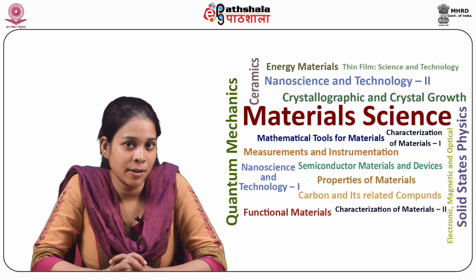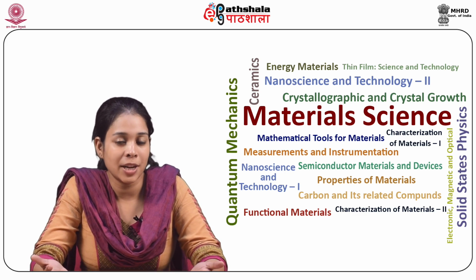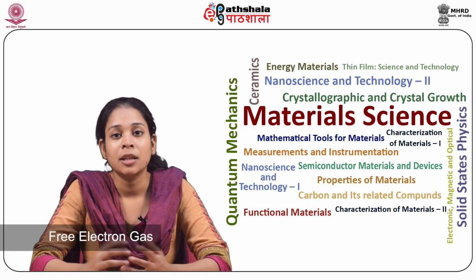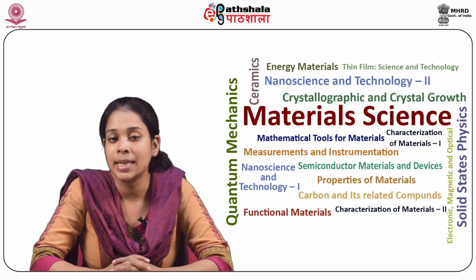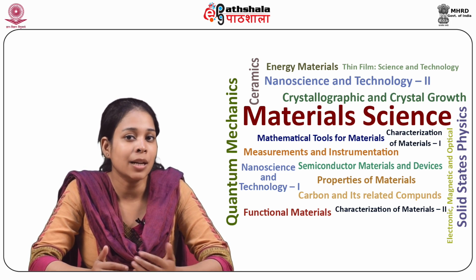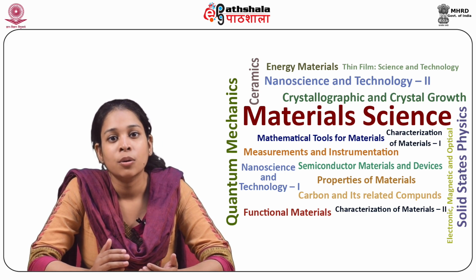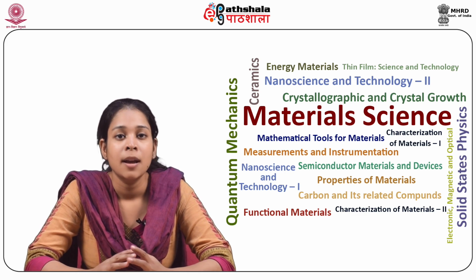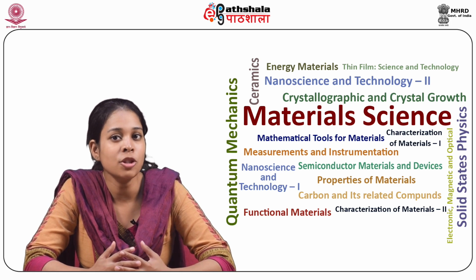So, now the first bonding is metallic bonding. This type of bonding is characterized by presence of sea of electrons around atoms in metal, and it is also known as free electron gas. The sharing of electrons is not complete enough to provide a covalent character and is delocalized. This very nature allows free movement of electrons around the metal cores whilst holding the cores together. This nature gives rise to flexible bonds, good malleability, high electrical and thermal conductivity, and the example is shown in this figure. Typically, most elements to the left of the fourth column in the periodic table show such behavior.